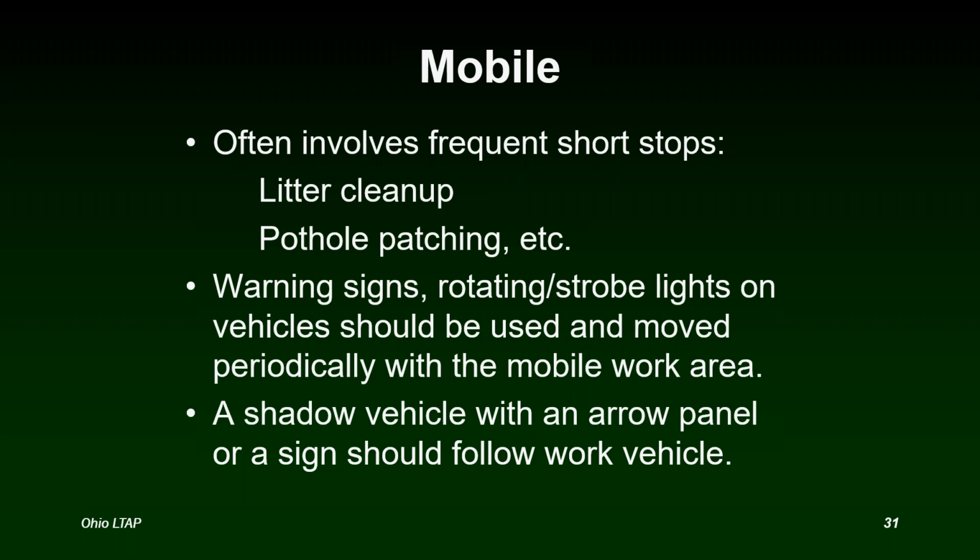So you have to consider the need for the shadow vehicle in your different situations, whether it's a low volume road or, sometimes even a low volume road needs a shadow vehicle. And that's when it's high speed, like our county and township roads, some of our state routes that are 2 lanes that are 55 miles per hour. And of course, the curves and dips in those roads are situations where the shadow vehicle is of the utmost importance.